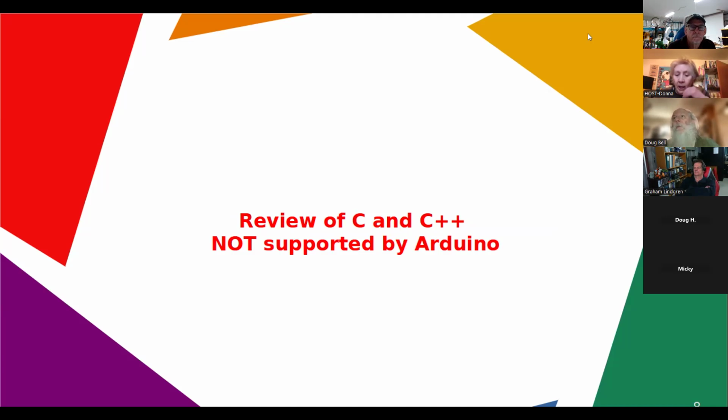Okay, so Arduino programming language is based on C and C++, but with some key differences and limitations, primarily due to the constraints of the embedded microcontroller environment. While Arduino supports a subset of C and C++, it omits features that require an operating system, file system, standard display, or keyboard, and instead provides Arduino-specific functions for hardware interactions. That's a key concept in moving from PCs into Arduino. Okay, so here's a breakdown of what's missing and why.